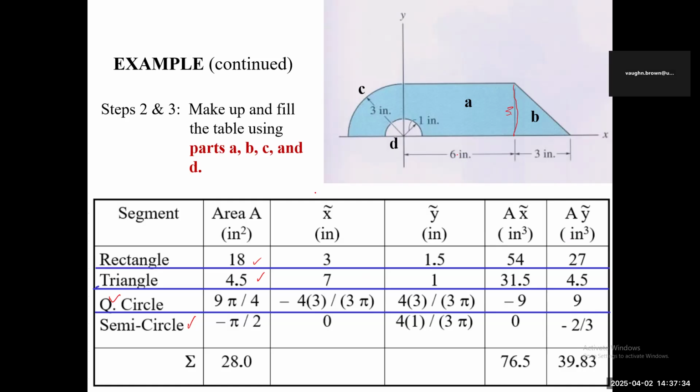But of course, look carefully, a minus sign is introduced in the box. Why? Because it is a hollow, or we call it a void area. So it's not actually there. That area will have to be subtracted from the total area. And therefore, that's how they got the 28. So they add the entire column here, remember? Add the entire column and you subtract that one. Don't add it. Make sure.